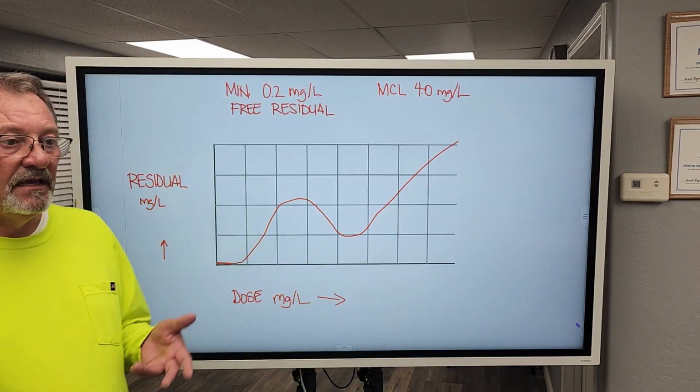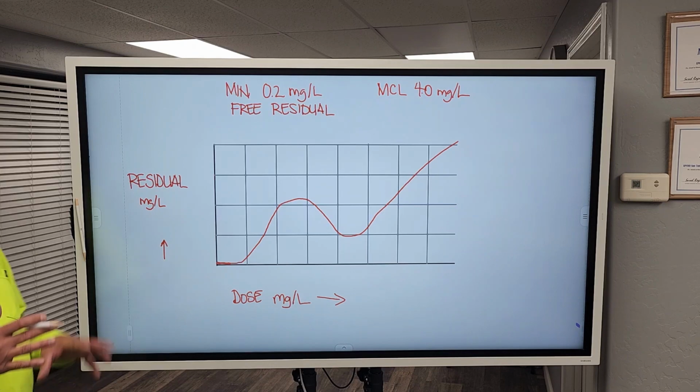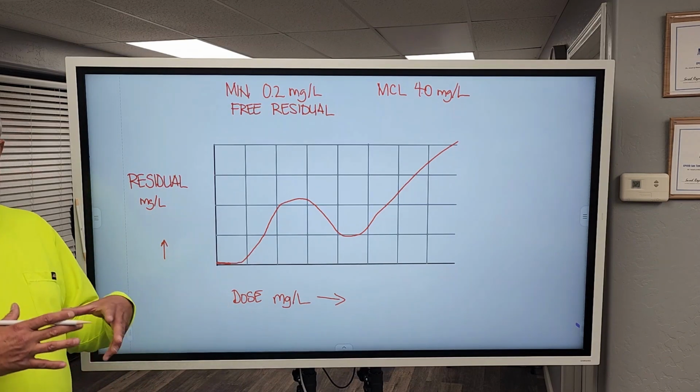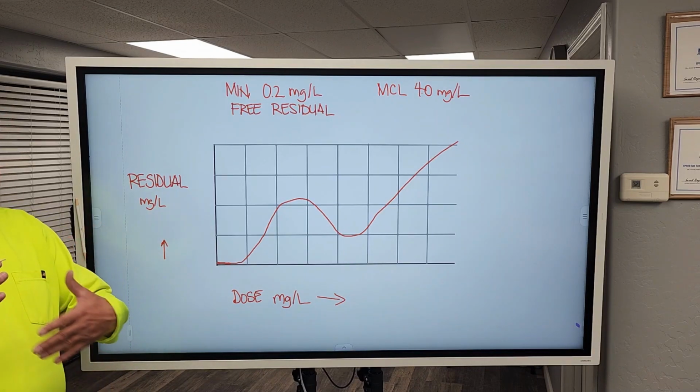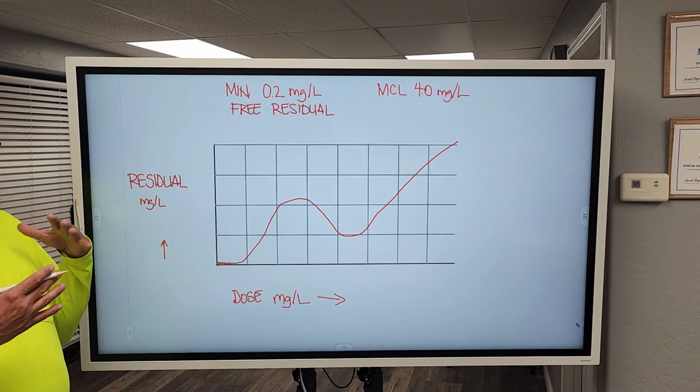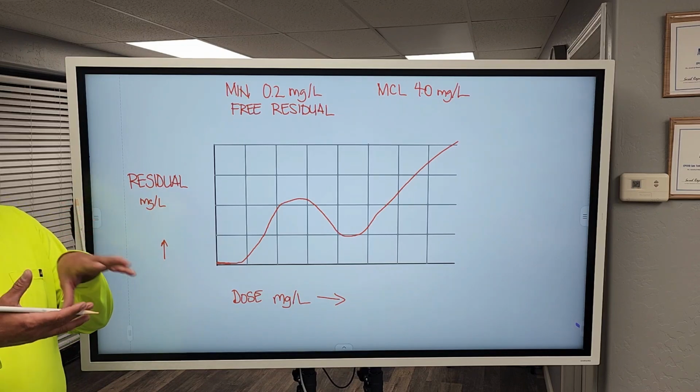It's even breaking down nitrate, right? So if there's nitrates in the water, it's trying to break that down first. So the entire dose of chlorine is getting used up right away. It's also doing all the other things that we want it to do. It's starting to combine and break down organics.